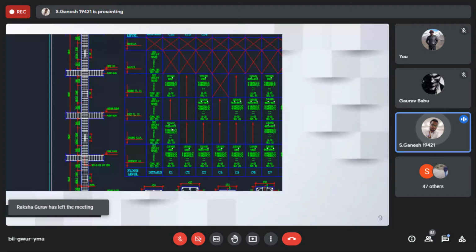The third is your column detailing, where you see a column building. On the third day I said column grouping. If you have 1,000 plus columns, we are not going to do the design for 1,000 plus columns, as I said earlier. So we are going to use the technique called grouping. That's what I taught you, the idea of why we need to do the groupings.